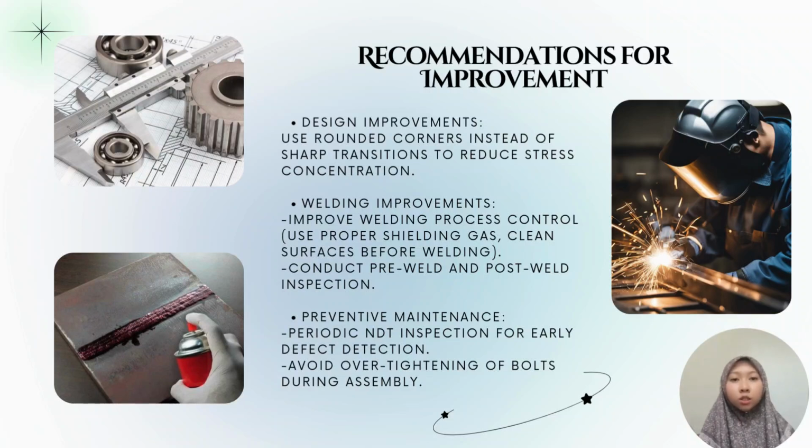Okay, second, welding improvement. We should enhance welding process control, including the use of proper shielding gas and cleaning the surface before welding. Additionally, pre-weld and post-weld inspection are crucial to ensure quality and detect early defects.